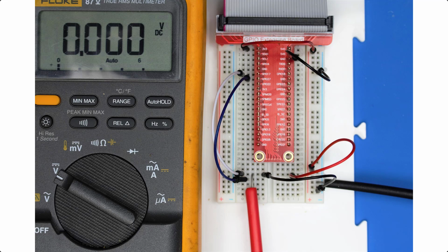Alright, now let's demonstrate what happens when we close the switch, or when we ground the pull-up resistor. So take that ground jumper wire and we're going to bring it over so that we ground row number 26. So now our row is grounded and we should see a voltage value of 0. You should also see on your terminal an indication that the pull-up resistor has been triggered.